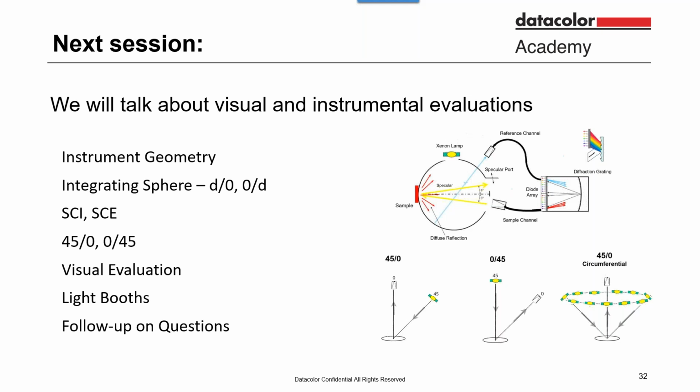But again, the tolerance really has to be a balance between what you can actually produce at a reasonable cost, and what your vendor, supplier or customer will be able to accept. With tolerancing, there are no hard and fast rules. It's really about whether you can measure it, and measure it repeatably, and based on those measurements, set parameters you can use for pass/fail.